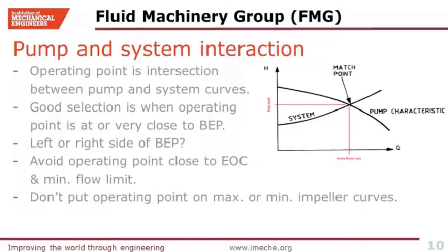All other points that we explained before, such as allowable or preferred operating regions, are somehow compromises which should be carefully considered when sizing a pump. Selecting a pump with an operating point at or near the left side of the BEP is a common practice. It is a conservative decision, but do not be afraid of running at the right side of the BEP point.